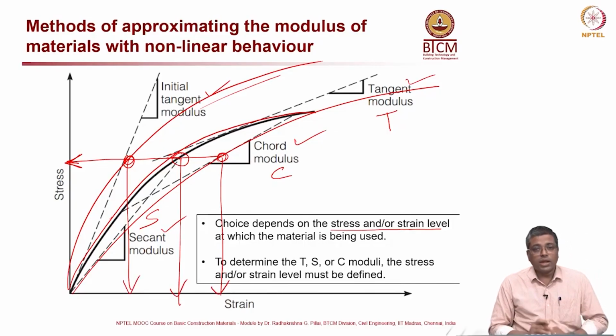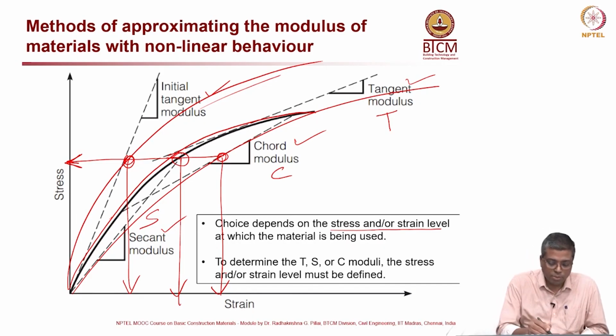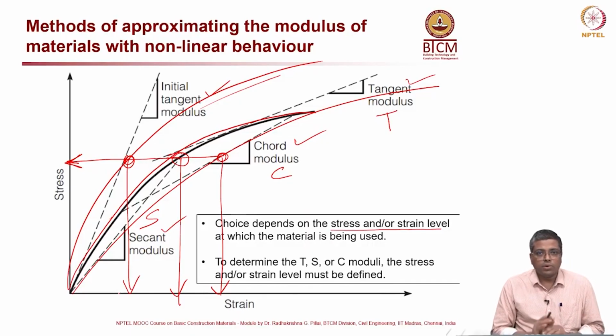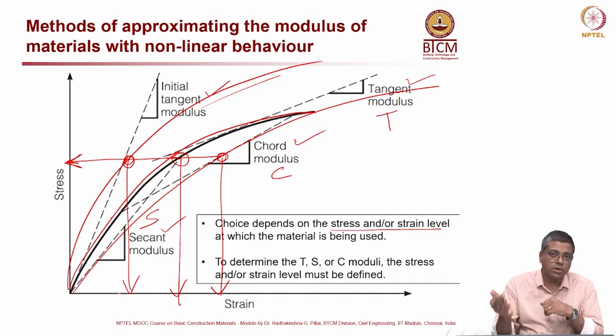Okay. So, based on that you can decide what would be the strain experienced by the material if my options A, B and C, 3 options, which I draw as 3 vertical lines here. So, like that you can get the stress strain behavior, the stress strain graph of various materials which are available for use, then decide the stress level which will be experienced by the material while in use, and then based on that you can decide which material to take, whether the strain is beyond the limit or not.